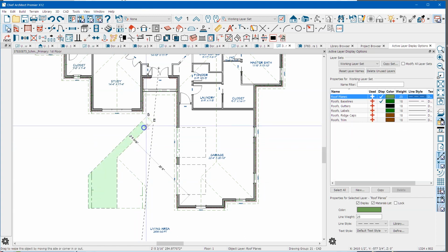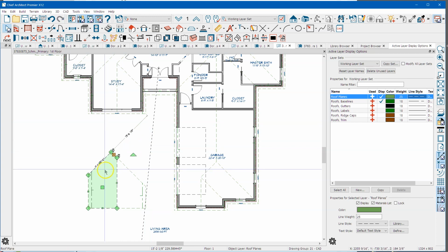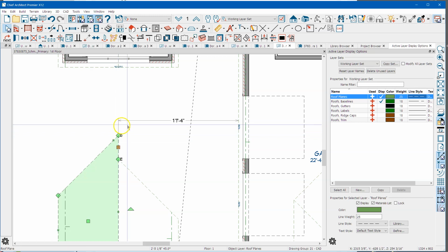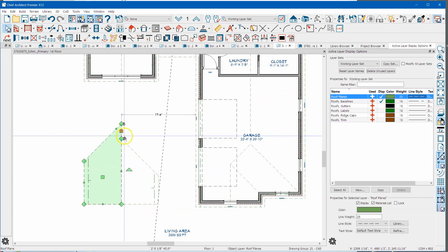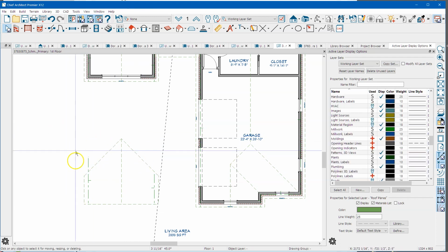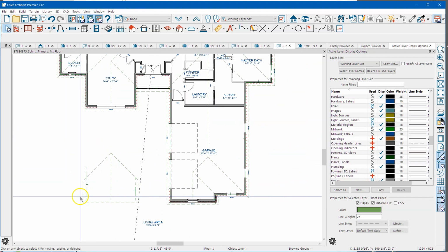And so you can do the same thing. Just drag this down here. Drag that up there, and you'll see I've got a little arrow, or a cross, where it lines up. And then you want to get rid of these extra breaks in here, so I'm just going to drag this down right there. And so that cleans up these two roof planes.